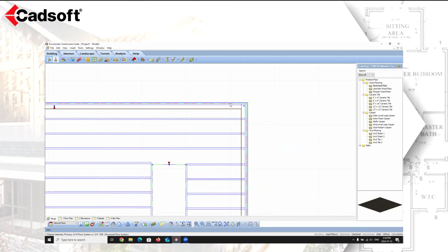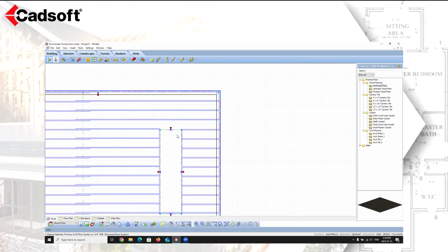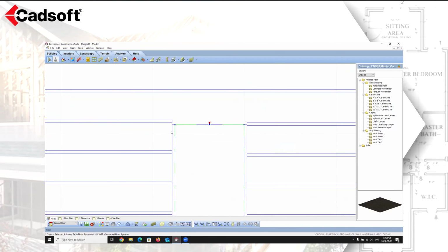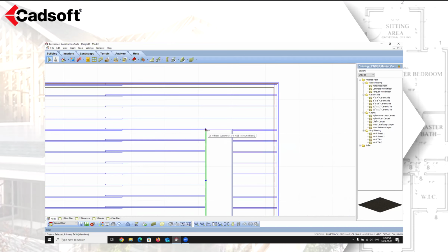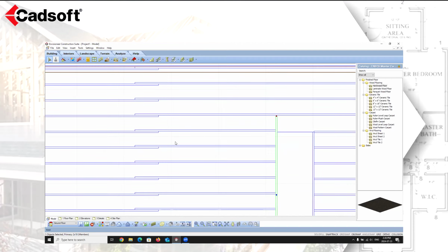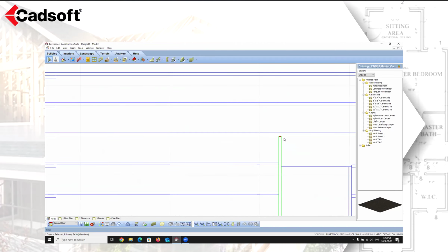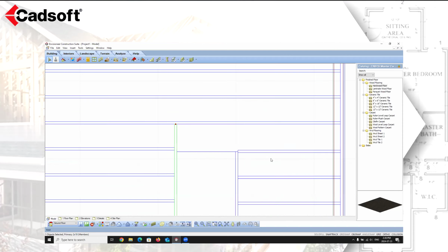and you can say, okay, now I can go through and I can start to adjust how this floor would actually be framed. I would probably take this opening and I would probably go all the way to the edge here. So I'm just going to bring that edge and I'm just going to use the grips here to snap to where I want it to go.